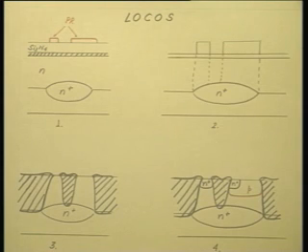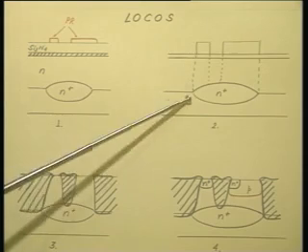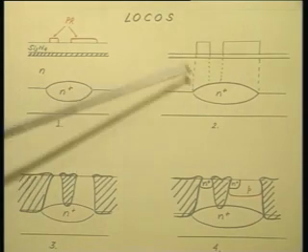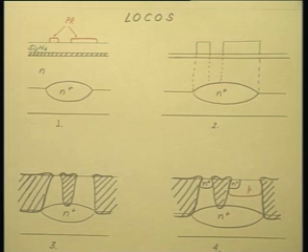because of lateral oxidation. See, when you are etching it down, two surfaces are exposed. One is the horizontal surface and the other is the side wall. So, oxidation progresses on both these surfaces. Therefore, there is a slight encroachment under the mask, which is actually called the bird's beak problem, because it looks somewhat like a bird's beak. But a bird's beak problem is not very severe as far as bipolar junction technology is concerned. We will discuss in more detail about bird's beak problem when we discuss MOSFET technologies, because there it will be more severe. We will discuss there how those problems can be minimized.